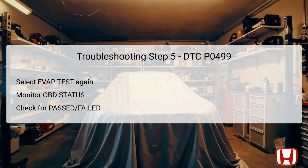In the final troubleshooting step, return to the HDS to select the EVAP test option once again. This repetition serves to ensure that the EVAP system is now working correctly following the PCM reset and idle learn procedure. Pay close attention to the OBD status, observing if the system indicates a passed, failed, or not completed status. A passed status indicates that the EVAP canister vent shut valve circuit is functioning correctly, while a failed status may require you to revisit previous steps for further troubleshooting.